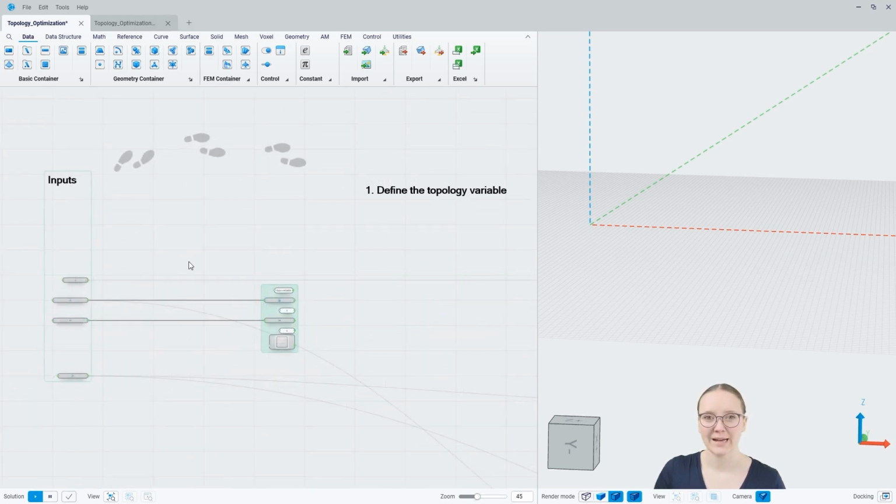Before we start with our first step, I'm just going to explain real quickly why we will have those two streams, the dimensioning and non-dimensioning optimization. So the dimensioning topology optimization is ideal if we have volume AM parts, and we will get less discrete designs. And this process is ideal to be reconstructed with the quad remesher process.